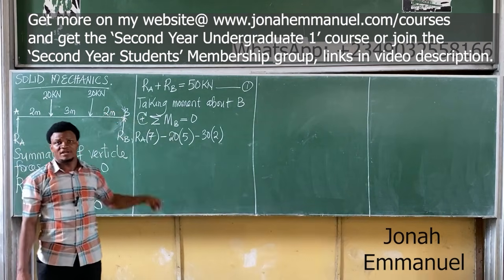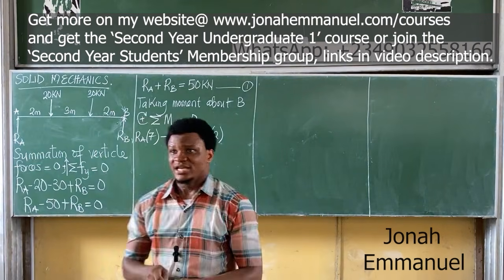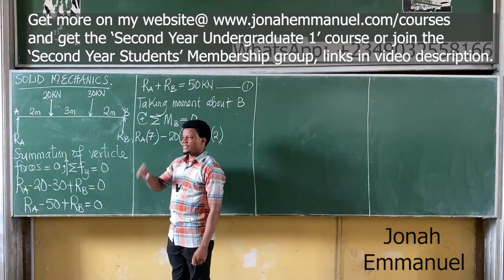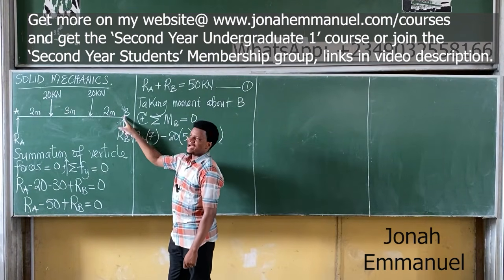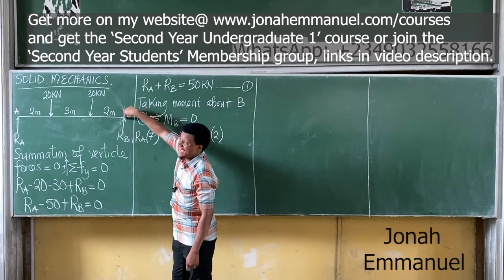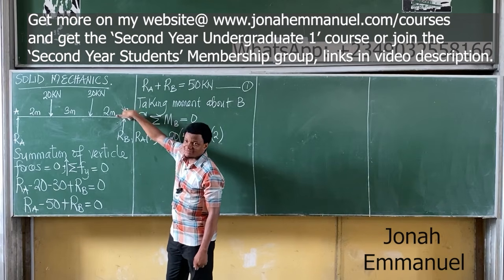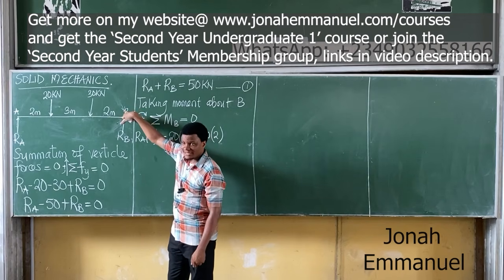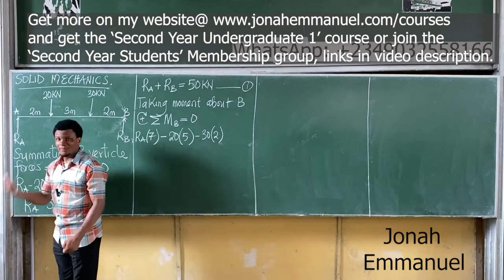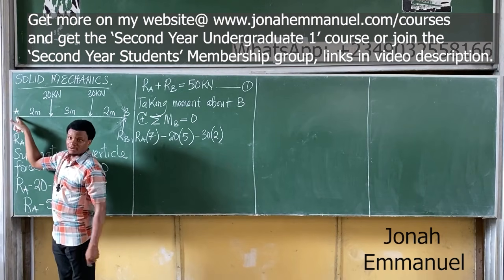When you're solving this, in most cases, they don't include RB. Know why? If I'm taking moment about B, I don't have to include RB because RB is exactly at B. What's the distance here? No distance. It's at that point, so it becomes 0. In essence, if I were to take moment about A, will I include RA?